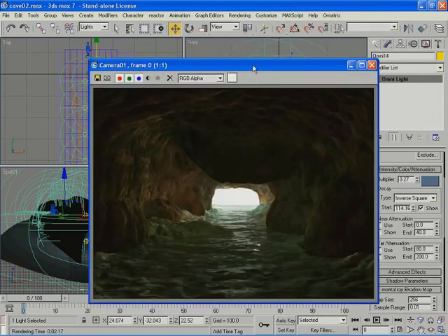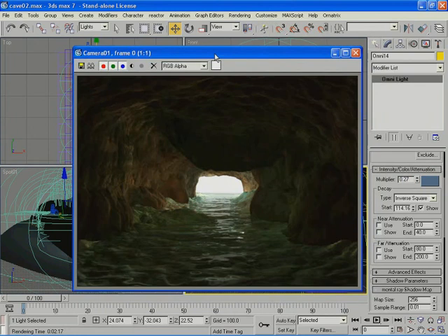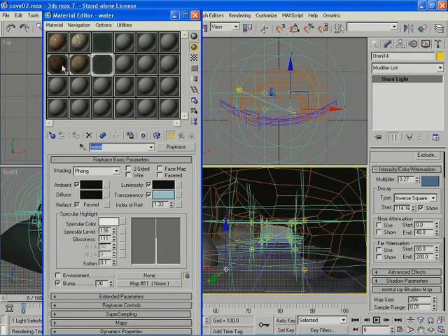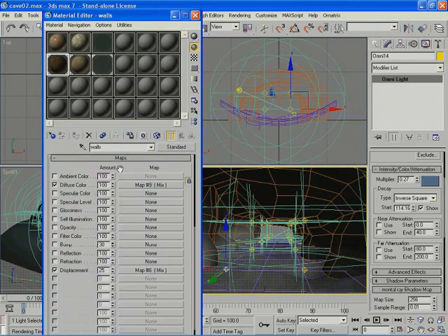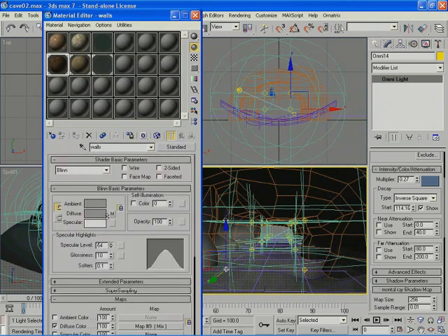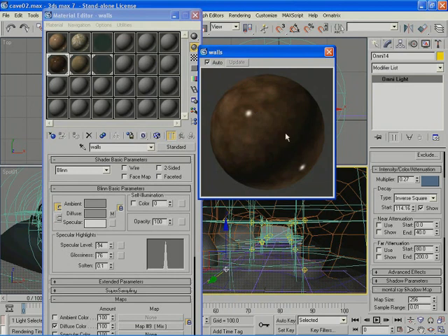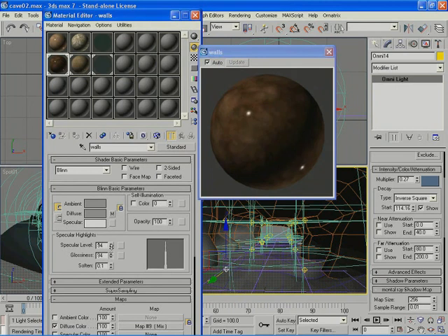Yeah, the other things I need to work on is to give some glossiness to the edges so that I get a wet appearance for this. So I'm going to take this material and I'm going to up the speckle level and the glossiness like this. So if I maximize this material, I need to make this as sharp as possible by increasing the glossiness value, because I don't want it to spread all around. So it needs to be sharp to give the impression of being wet.